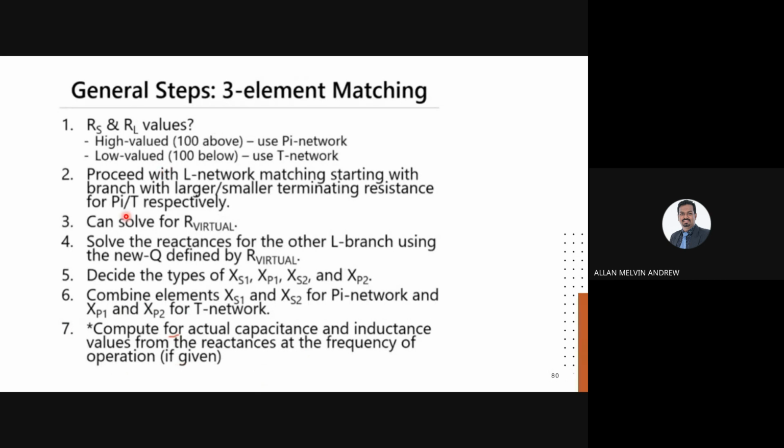These steps are for practical transmission in the industry. You first have a modulating circuit that you already prepared, and you want to join it with the antenna, so you need to find the impedance matching. Once you have the impedance matching, then you can send the signal at the frequency of operation, let's say 100 megahertz.